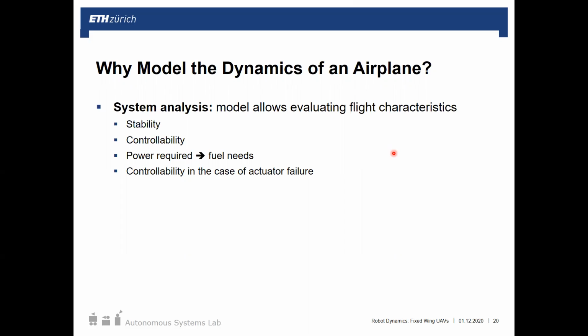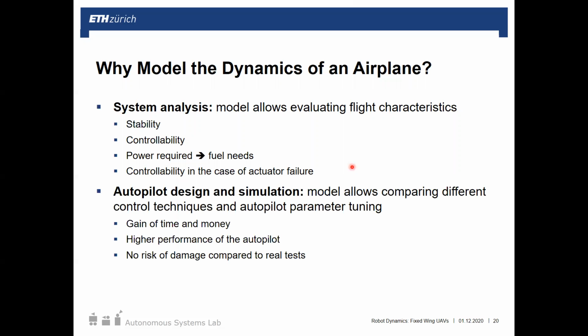Of course, if we have specific missions that we want to accomplish, let's say long-range missions or long-endurance missions, having a model of the aerodynamics will then tell us how much power is required for these things, so either fuel or batteries. And then let's say, for example, we have an actuator failure during a flight. Having this model again would maybe allow us to define some maximum bounds of, if we have a stuck aileron, what moment it might generate in the worst case. So we can be prepared to compensate this.